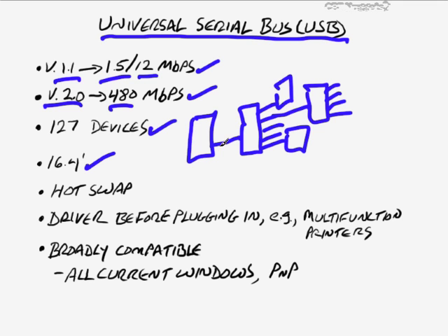You can use these, generally speaking, as powered or non-powered. If they're non-powered, then they depend upon power from the originating USB port back here. So if this is a non-powered one, and then I've got another hub out here, and it has to supply power to devices, then you probably need to power this one in order to be able to supply power out here. Otherwise, you're extending too great a distance the ability for that USB power to extend out. Sometimes you can also cheat this as well.